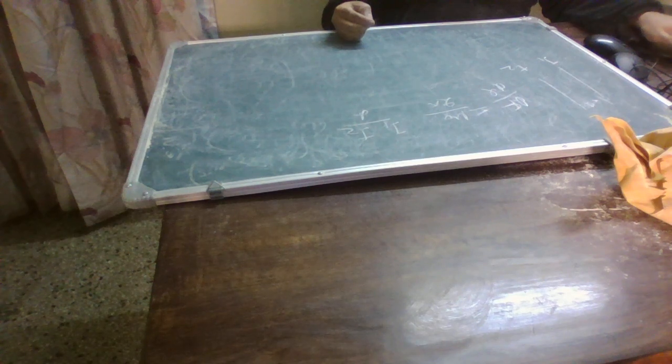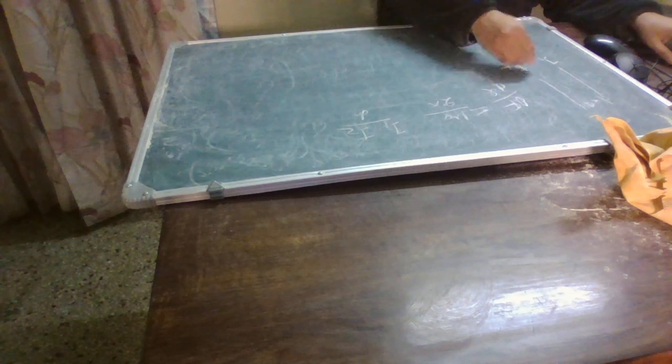The force is attractive if the currents flow in the same direction, and repulsive if the currents flow in opposite directions. The force exists between the two current-carrying wires, and we can use it to define the magnetic flux density in a way that is independent of permanent magnetic dipoles.